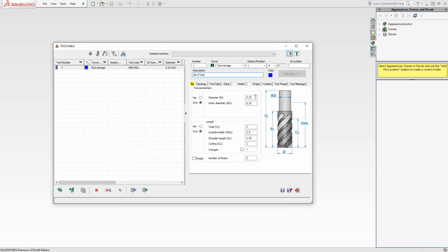Further along here, we can provide dimensions. I'm just going to define my tool as a 1/2-inch tool with a cutting length of 2 inches. If these numbers don't make sense, according to this icon on the side here, in this case my cutting length being 2 inches cannot be higher than my shoulder length, it will actually give me this error in the bottom left corner. So I'll just go and correct that. Let's make that 2 1/4. So now that tool is correct, that tool is defined. It is now part of this global archive tool library. Going forward, in any milling operation or any mill turn operations, I can pull from this list and add that to an active tool library.